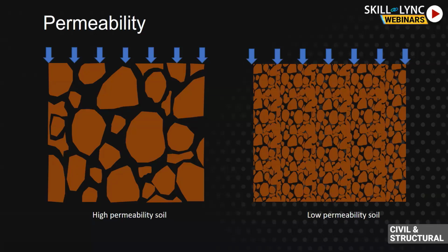So, for instance, I've been working in Singapore for quite some time. Here in Singapore, it can be as shallow as 1 meter below ground up to 3 to 4 to 5 meters, and in some mountainous areas it can be much deeper. Below the groundwater table, the void within the soil will be occupied by water. This is called pore water, and this water within the pores induces pressure on these solid particles, which we call pore water pressure.